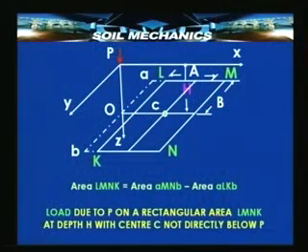This diagram, the next one for example, illustrates the case where we want to determine the load over again a rectangular area, but the center of this rectangular area is no longer under the line of action of the load or the point of action of the load P. In this case, what is required is to apply Boussinesq's theory, either the formula directly, or if the values concerned are within the range, then the point load influence coefficient table.